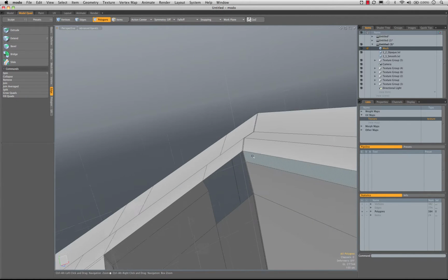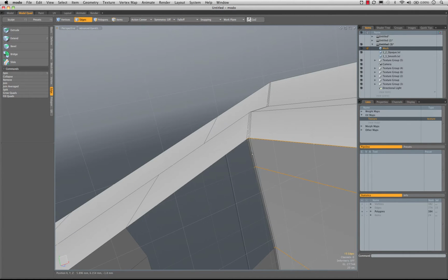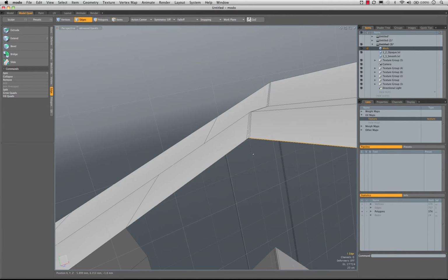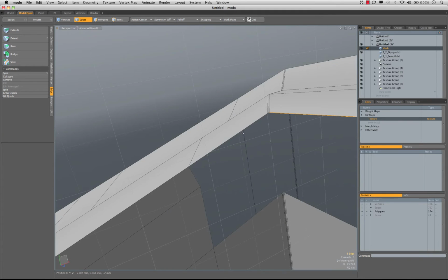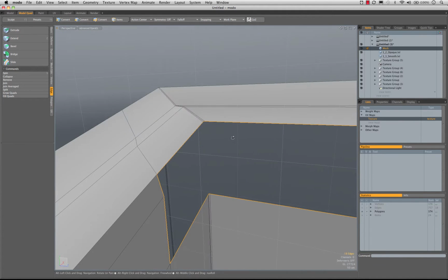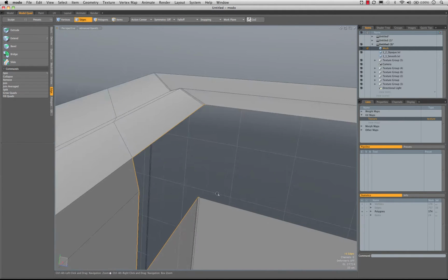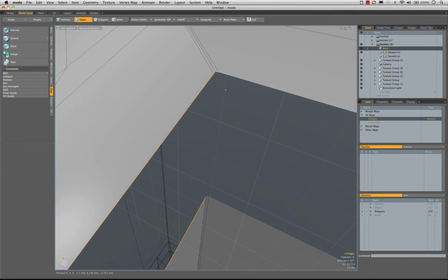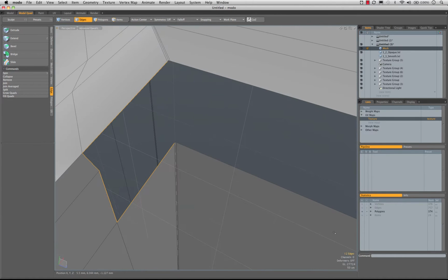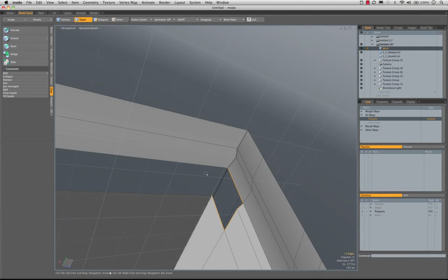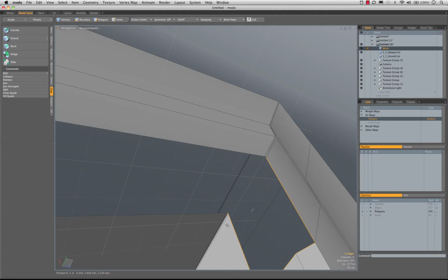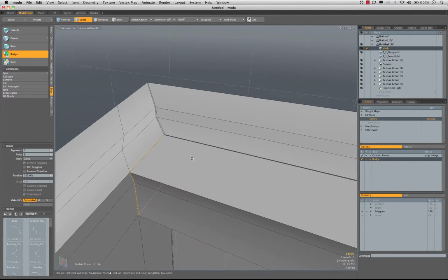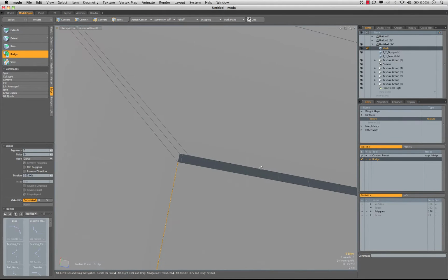And oops, actually, I've bridged together the wrong part. Knew something looked wrong about that. So it's like this entire loop. Wow. And I need to deselect these corner sections. Same thing will apply here, but we need to bridge across it to create the slat, so it's okay. Let's go ahead and get rid of those from our selection. Now we can run the bridge. Okay, and now we have